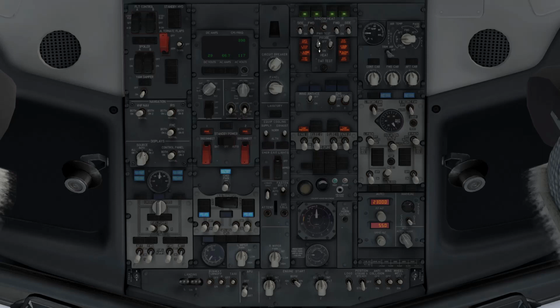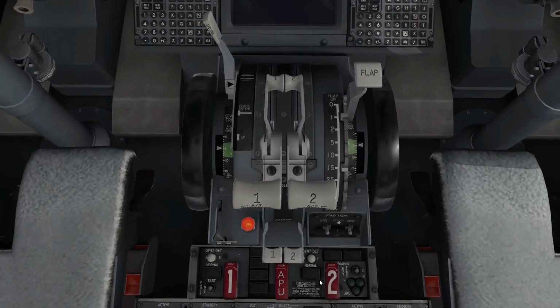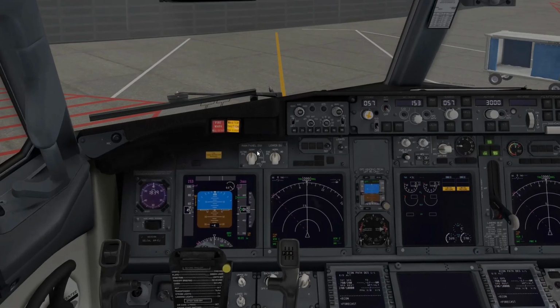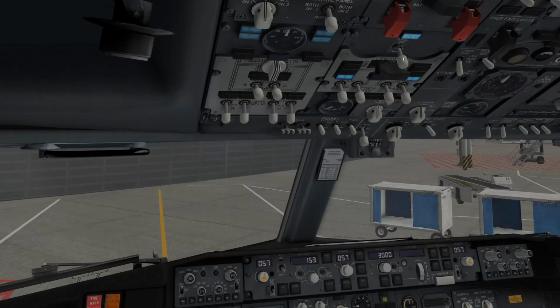The first officer would come up here and turn the electric hydraulic pumps off, so probes, anti-ice, hydraulics. Turn the APU bleed on, and that will get conditioned airflow since we turned off the engines. And last thing would be to just come down here and turn the transponder to standby. That's pretty much it.